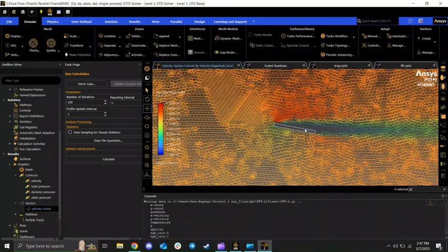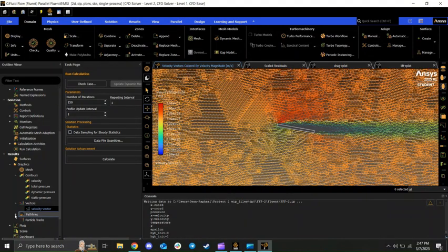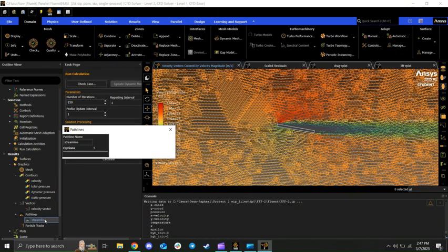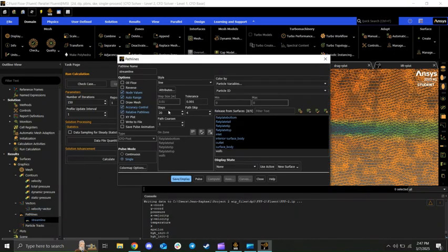Okay. Now, if you would like, you could also do the same thing with path lines. So, double click path line. I dubbed this a streamline. Selected all the surfaces, except for walls, particles, particle ID, save and display. Again, this is just a different way of seeing flow in the wind tunnel itself.